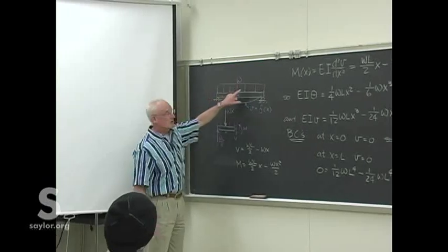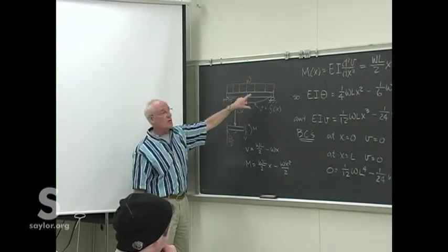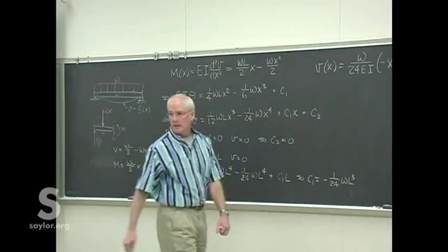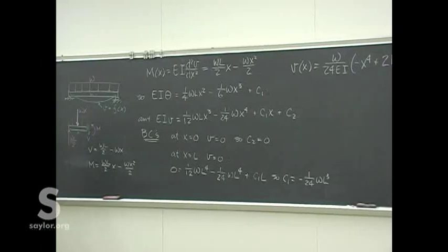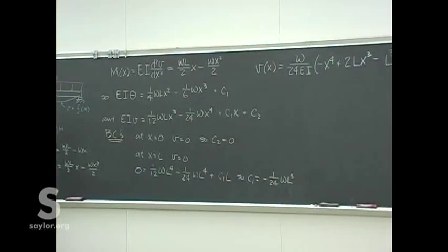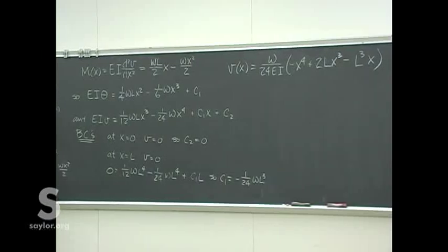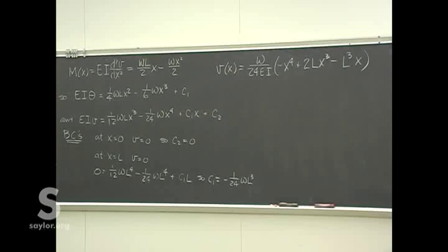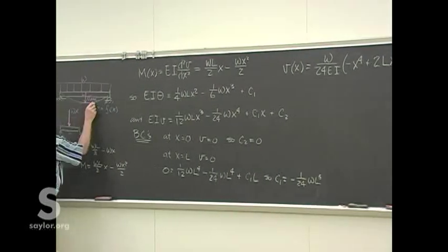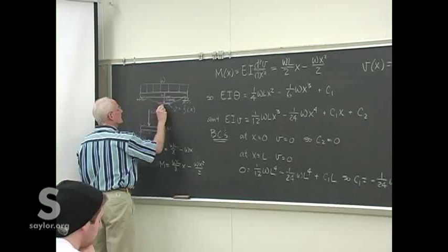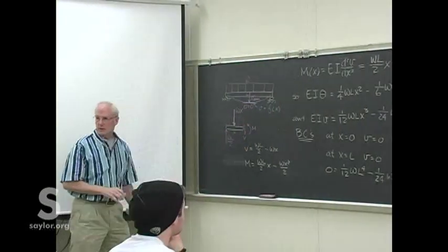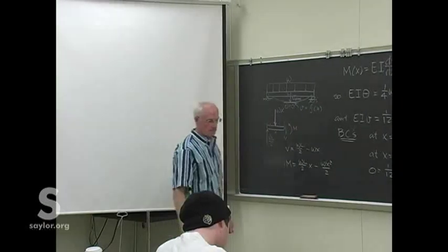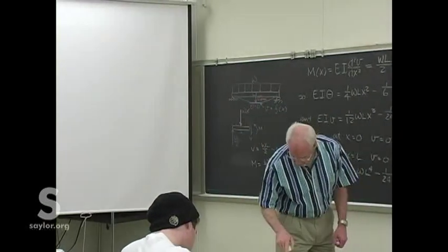So we could figure out, unloaded just by the beam under its own weight, what its deflection will be at any point. By symmetry, we also know that the maximum deflection will be right there in the center where the slope equals 0. And so we can figure out just what that would be for various values.